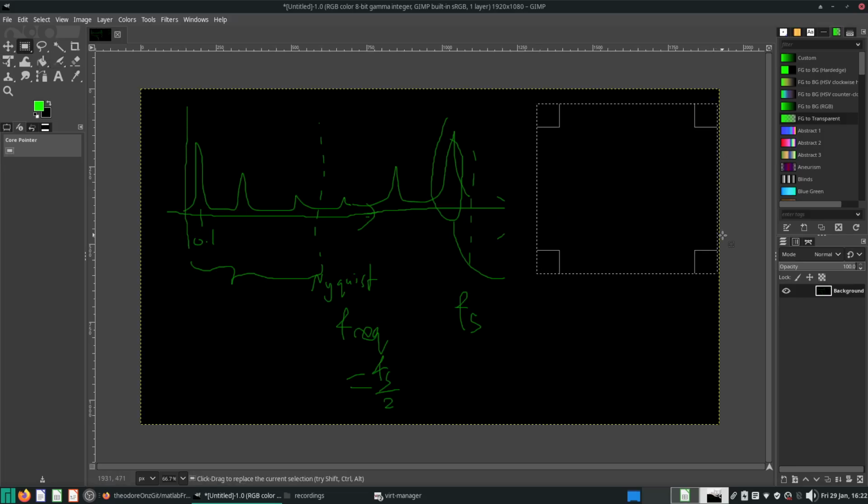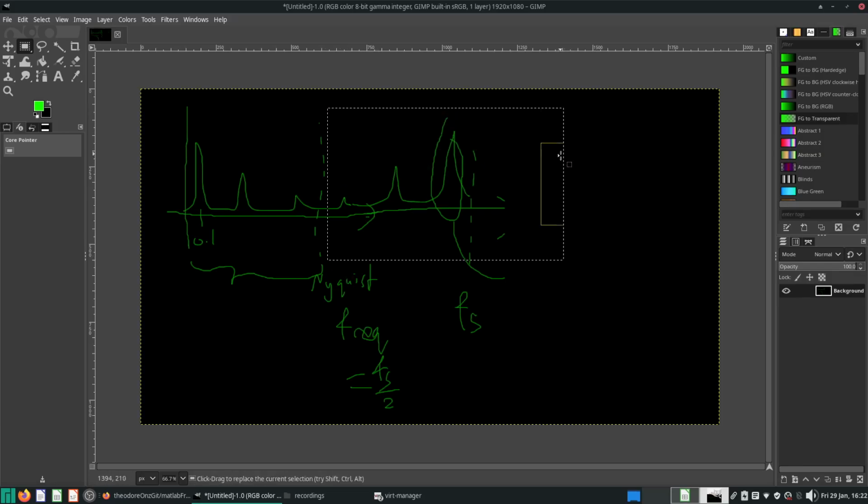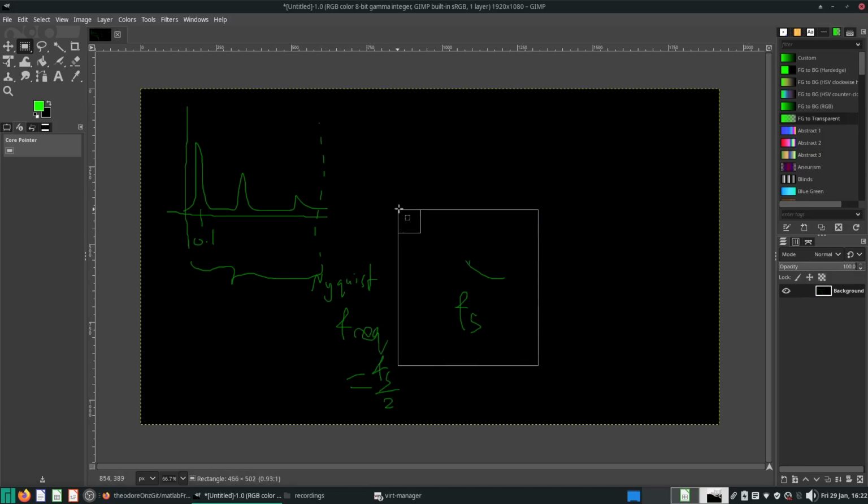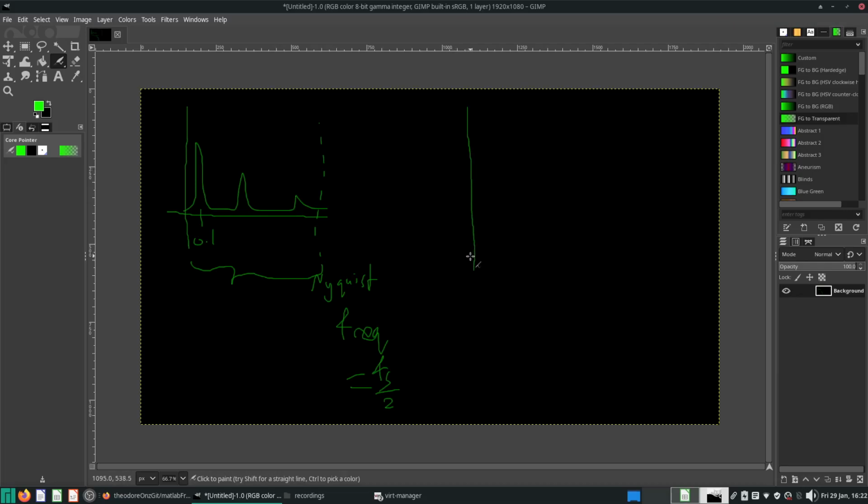Enough of that. That's just a refresher on what the plots look like, with your sampling frequency and your Nyquist frequency. The problem, of course, is that when you have a non-uniform fast Fourier transform, you will not have a so-called sampling frequency. Let's say you have time equals 0, 0.1, 0.3, 0.6, and all sorts of data here.